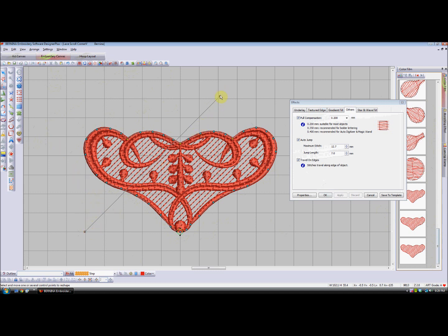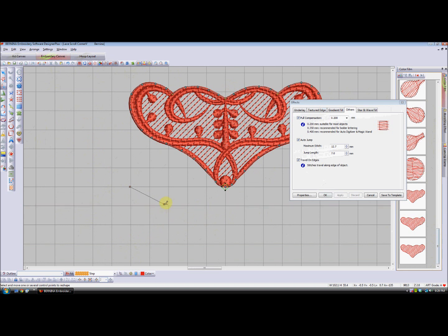So we can do this two ways. We can grab our angle tool and bring it round and fiddle around here till we get to 135, and it went to 136. So you can see that can be a bit problematic. I've got it on 135, so I'll go OK. I'll enter, and that will turn it in the opposite direction.